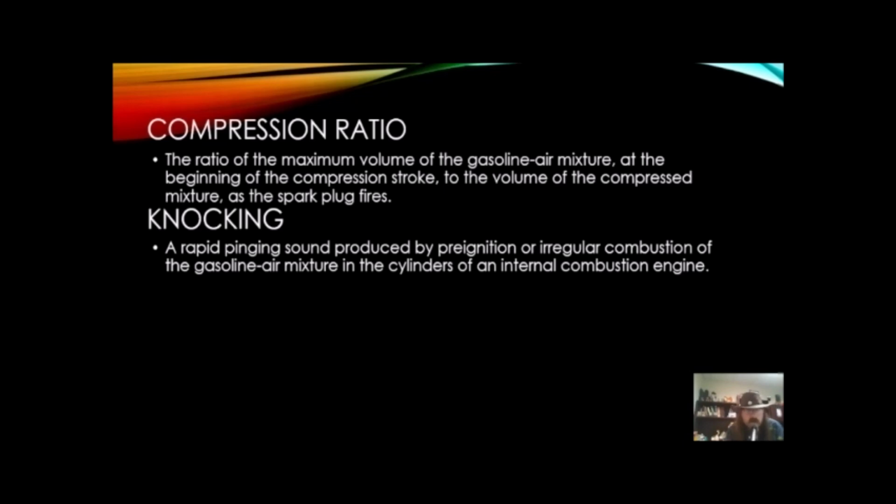It's knocking. You may have heard of this term, you may not have, but it's a rapid pinging sound that's produced by either pre-ignition of the gasoline or irregular combustion of the gasoline-air mixture in the cylinders within an internal combustion engine. Essentially, this problem occurs under high power loads, like if you're accelerating, especially uphill, if you're towing something really heavy.